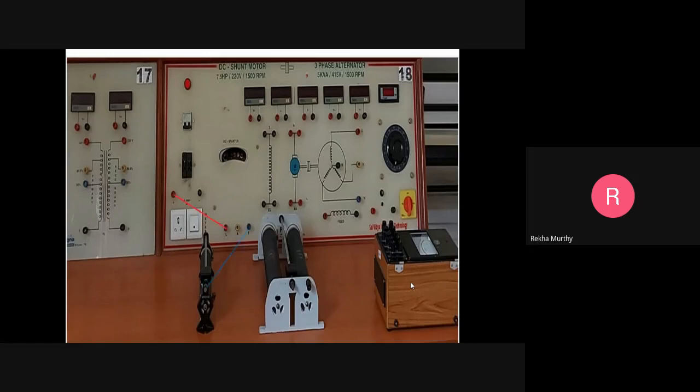Now let us see how you are going to do the connections. The positive supply is connected to the L point of the LFA. So first I will finish off the LFA. Then F is connected to the rheostat of 600 ohm. The other end of the rheostat is connected to the field winding Z. The other ZZ terminal is connected back to the negative supply. This closes one loop with respect to the line, completing through the field connection and coming back to the negative supply.